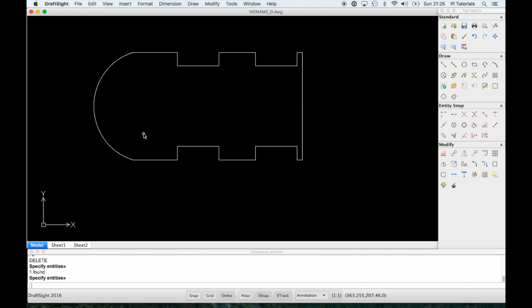So you can see very easily we can draw stuff to very set dimensions by using offset and move. You could draw it in relative coordinates or absolute coordinates. It's entirely up to you, but I know precisely how long these lines are. There's no worry about guides. I can draw lines in to use as guides and just offset them and erase them. It's all very flexible.